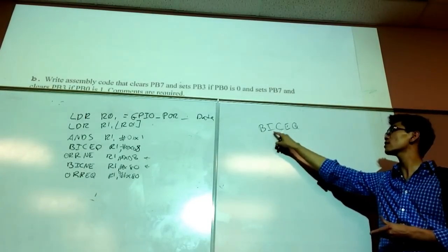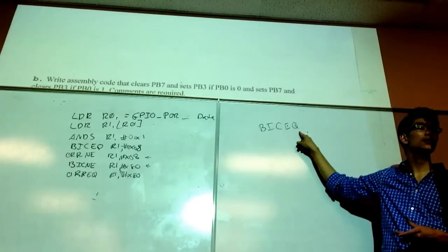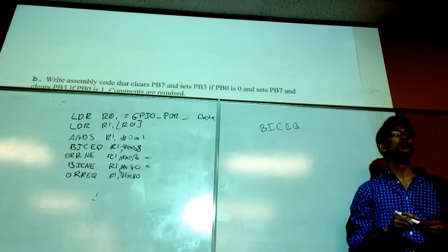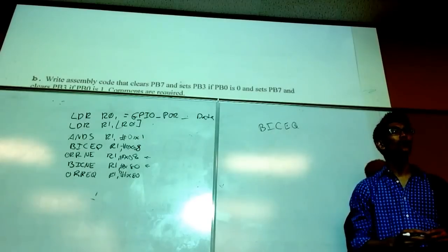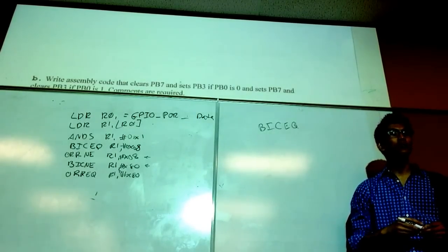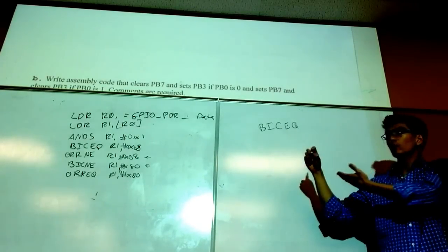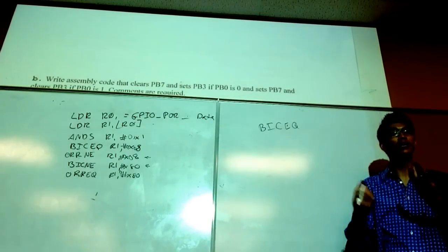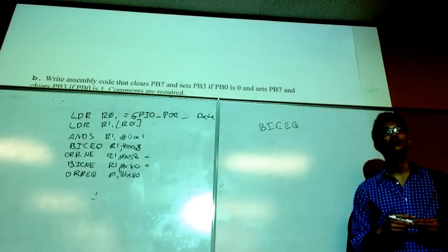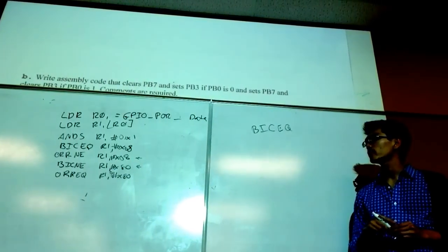So this is saying execute this instruction if the equal condition is valid. You can do that for basically any instruction in the whole instruction set, which can make your code a lot simpler. So instead of having to branch to perform one instruction, you can just have that one instruction EQ, or NE, or LO, or GT. Those don't have to go in order.